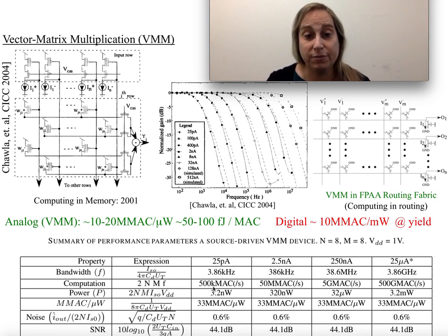One of the things you'll notice is very critical is the per unit capacitance, because you might imagine the more capacitance, the lower the kT over C noise you have. It also changes what your speed is. So again, all the classical analog design concepts come into play. If you go above threshold, these certainly do change. In most cases above threshold, it's a diminishing return problem. But otherwise, you get a very, very reasonable thing, and you can design different structures for different capabilities.